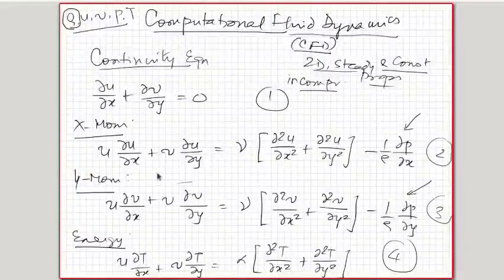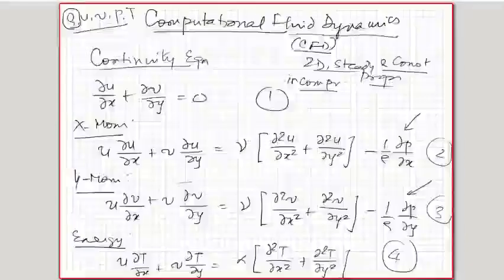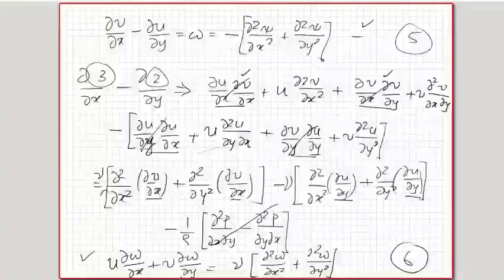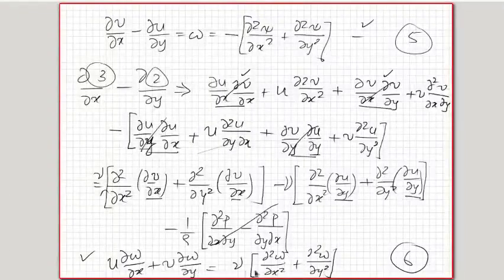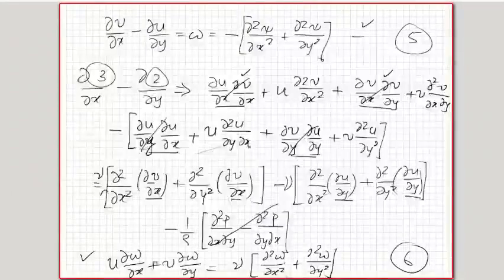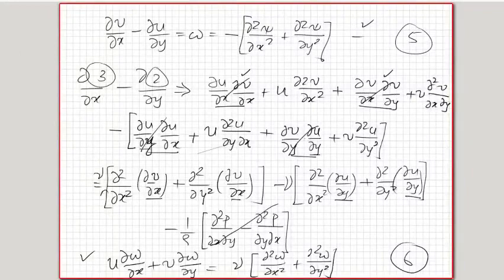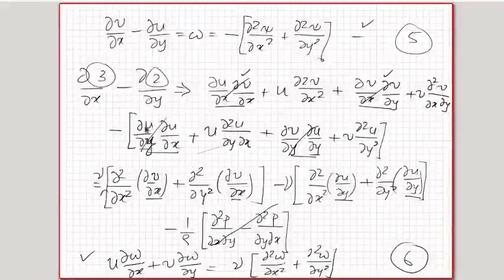Look at these equations, and we said that these equations look quite similar to each other. When we derive the vorticity equation, it also looks quite similar to that. Equation number 6 also looks quite similar. So the method that I'll be using for solving these equations is to do the discrete equation integration over a control volume, so that you understand how the equations actually are solved.